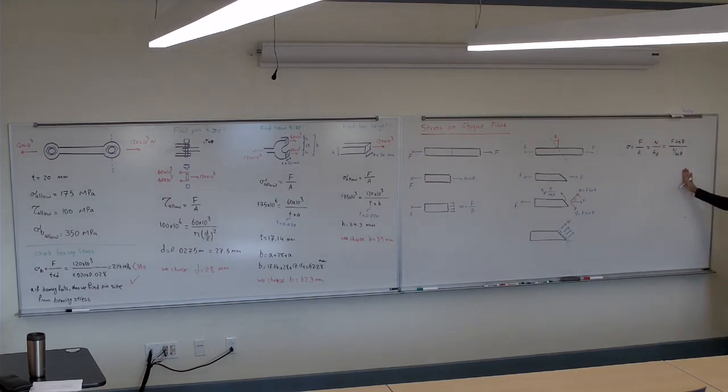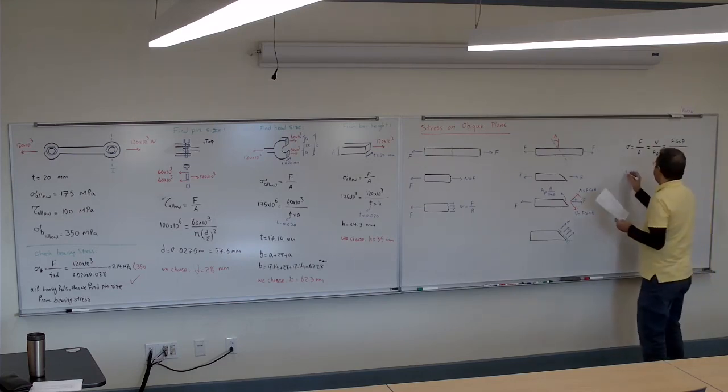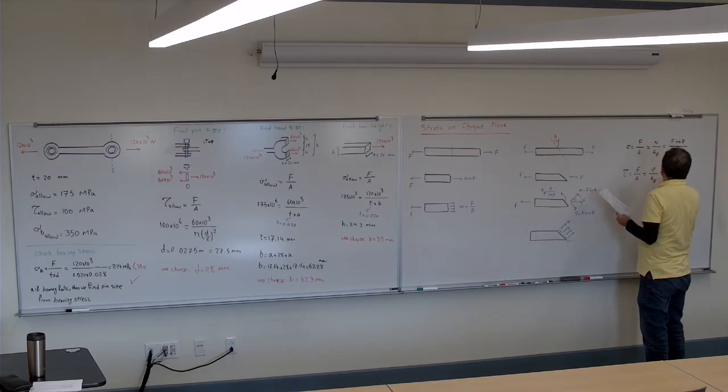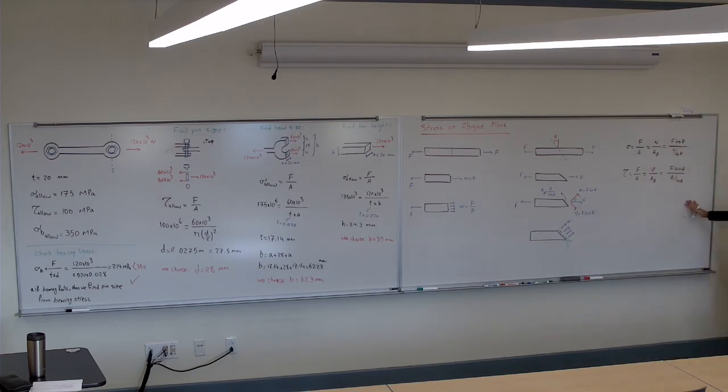Agree? So the shear is also again force divided by area, which is V divided by A theta, which is F sine theta divided again by A divided by cosine theta. And the first one, can't you write as F cosine squared over A? Oh yes, I'm going to simplify it. Oh, okay. I'm just making sure that wasn't a reason or something.